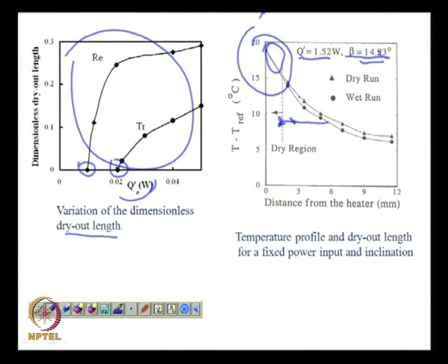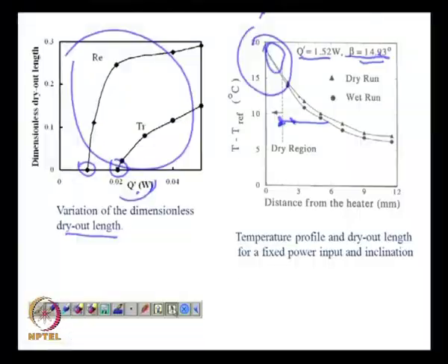But more importantly, the model equation can be used as a design equation, a parametric equation by which you can vary several things, including the number, the length, the physical properties of the liquid, the heat duty, and you would see how much heat you can actually extract till you reach the capillary limit.